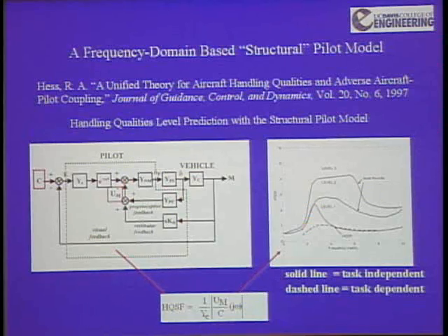Okay, one of the models I've developed and been using for a long time, this first came out in '97, was something called a structural pilot model. Output here might be the pitch attitude of the aircraft. This might be some pitch attitude command. There are 3 feedback loops, a proprioceptive feedback loop, a vestibular feedback loop. That's where the pilot's inner ear sensors are working, the otoliths and the semicircular canals, and down here visual feedback.